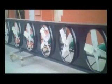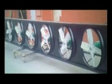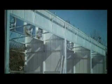Hot air traveling at high velocity throughout the chamber heats wood faster and more evenly, generating more uniform treatment and shorter cycle times. The optimum cubic feet per minute of air circulation is a function of the BTU capacity of the heating unit, the volume of material being treated, and the design of the treatment chamber.